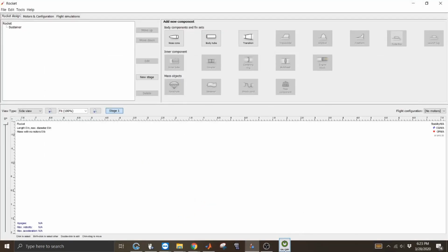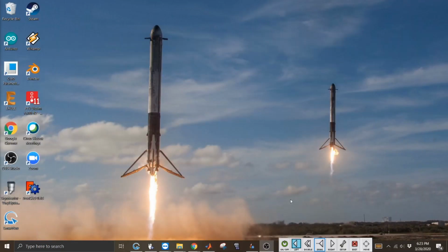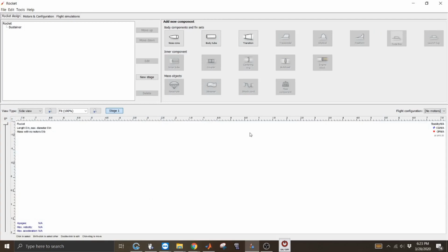So with any rocket, if I go back to our little picture here, the outside structure is pretty much comprised of a nose cone, an airframe, and then in model rockets you have some sort of fins, but in these rockets you don't need fins because you have thrust vector control in order to keep the rocket stable. For this design, we're going to include fins for at least the development of the control stages, but the fins are going to be removable. So once we have a working controller that can maintain stability, we can remove the fins and we know that it's going to fly straight. So for now, we're going to start with a rocket that has fins.